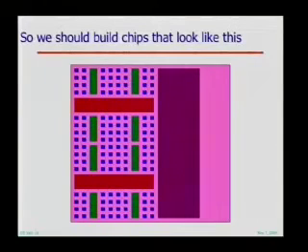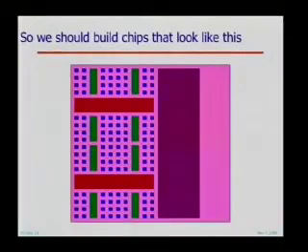Those are the little blue dots. And since we need to feed them locally, we need to put registers right next to them. That's actually included in the blue dots as well. Think of every blue dot as a floating point unit and a small number of registers sitting at every input of that floating point unit. And then what you need is a hierarchy, because when you can't keep the working set in those sets of registers, you need another set of registers close to it. So when you sort of need to stage data in here, you need to go to that register set.